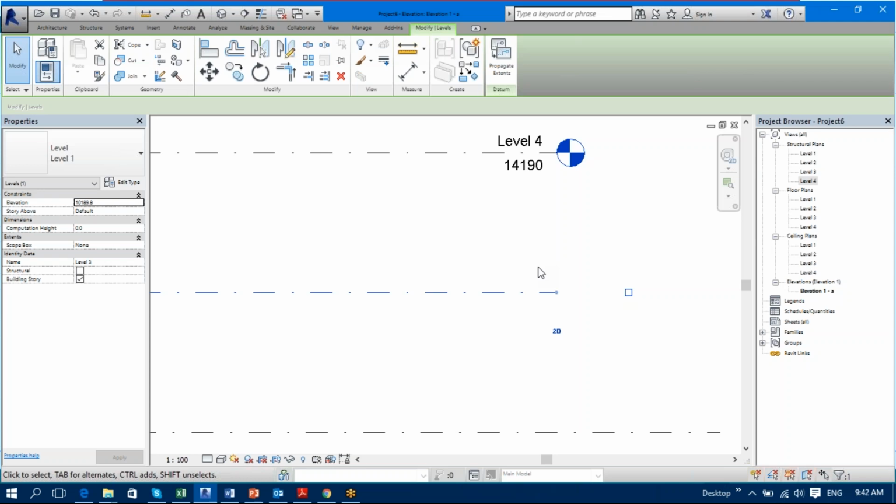If we talk about levels here, the moment I change this 3D to 2D by clicking on the 3D part, you see what happened. This small little point shows up. This is called a node, and the 3D padlock disappears.